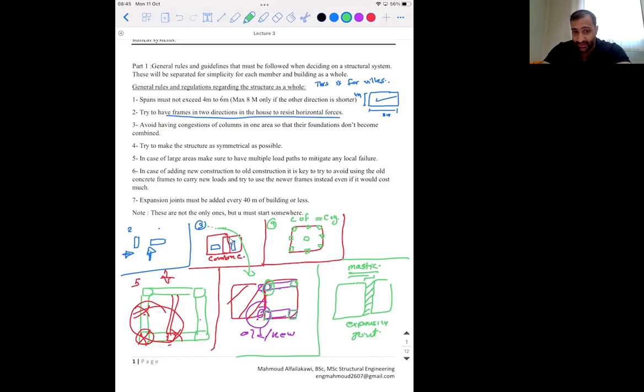You have to have, for example, a combined footing system. You have to compensate with cost. You're going to have old and new. You're going to have cracking, and you're going to have to mitigate for that with a lot of things you could do. But yeah, expansion joints, again, cracking, and maybe even one of them will go over the other.